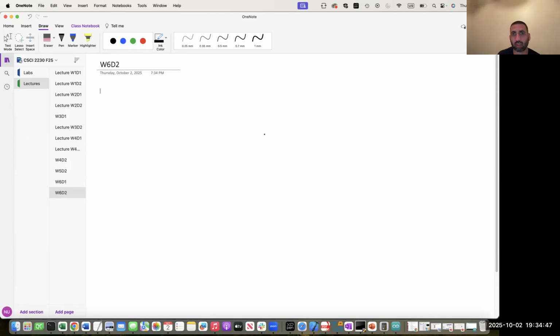In the AVR microcontroller, at least in ATmega328P, the total size of your memory is 32 kilobytes, which basically means 2 raised to power 5 into 2 raised to power 10, so you have 15 bits to address any location in the memory.